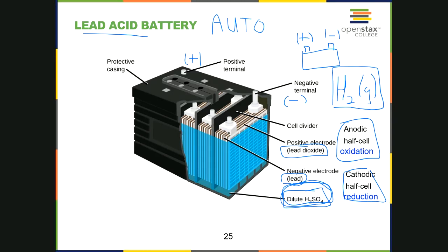So the way to go about this is, first you make a connection with the jumper cable between the donor battery and your battery. So you connect the positive to the positive. Now make sure it is actually positive and positive. If you go positive and negative, you're going to destroy your battery and the other person's battery and maybe their charging system and all sorts of stuff. Also, you want to make sure that the donor battery's automobile is not running. You want it turned off. Okay?